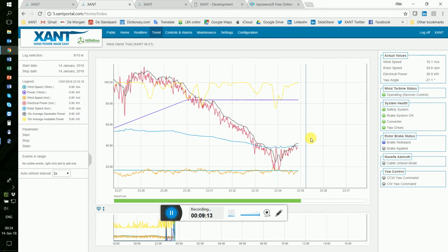This is a process that we're perfectly controlling thanks to only the torque control in the converter, which is imposing a torque on the shaft of the generator. There's no need for a dump load. There's no need for a pitch control. There's no need for braking. There's no need for managing that energy. It's just being curtailed. It's being shed at the very source of the power, which is at the turbine blades, by running the turbine at different CP coefficients. So it's a smooth process that doesn't take any additional hardware.